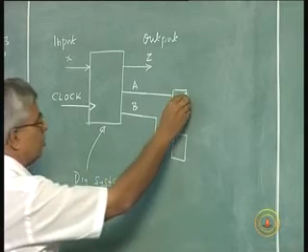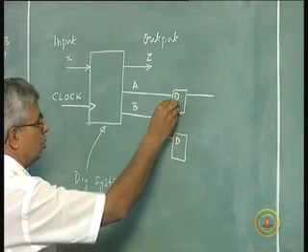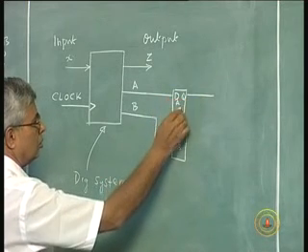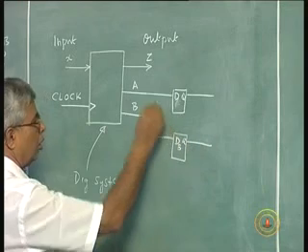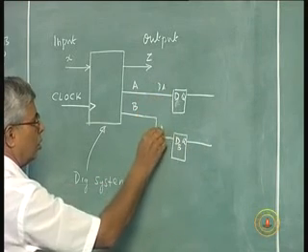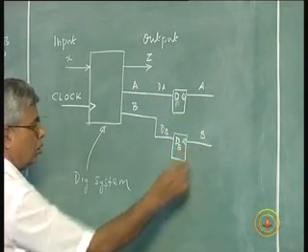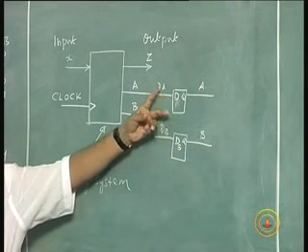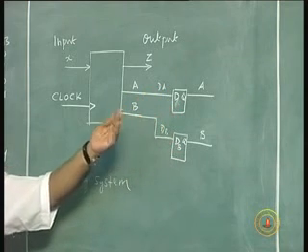And the values will be given to, let us say, simple D flip-flops, DA and DB. And since the circuit is now in state AB, which is 0, 0 or 0, 1, whatever it is, and it has to go to the next state,